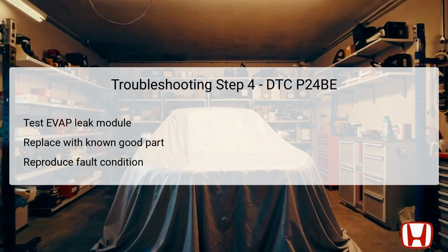If the error persists upon testing with the new module, it is likely that there are issues with other related components tied to the overall system. Conversely, if the DTC clears, this directly points to the evap leak check module as the source of the problem.